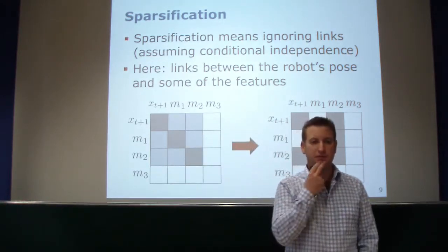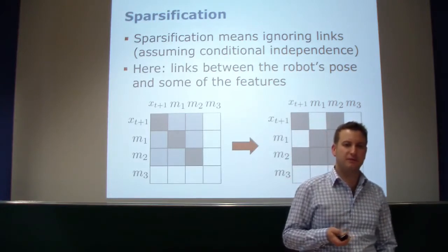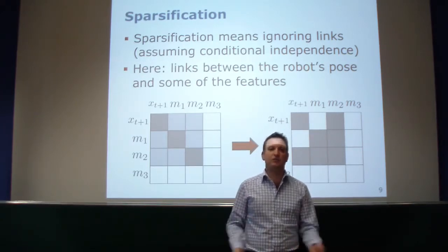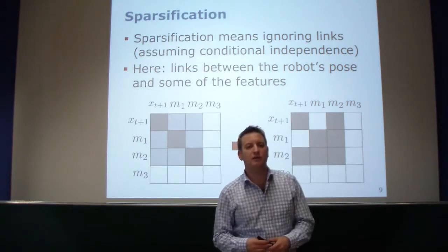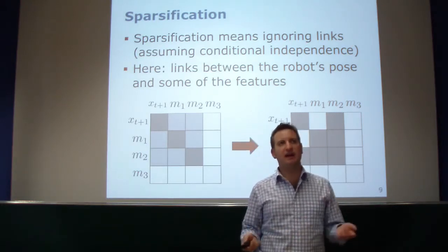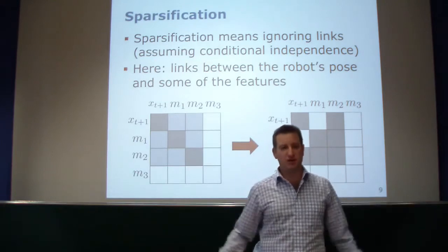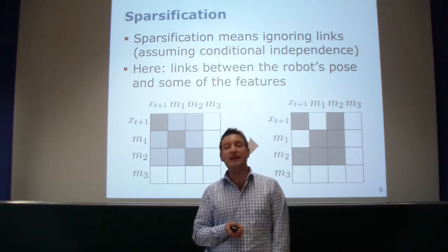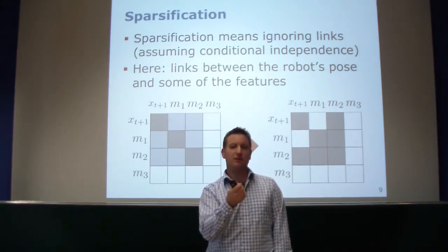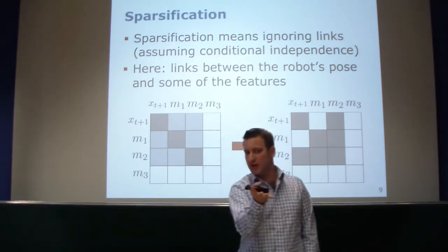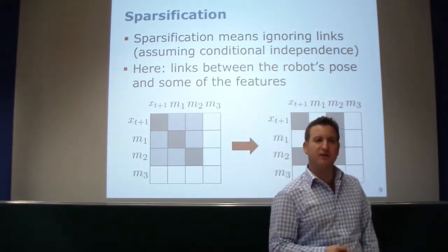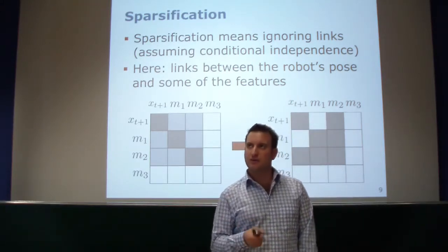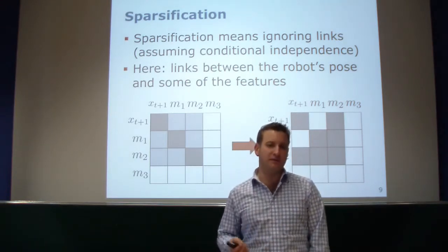Are the active landmarks just the observable landmarks? Not necessarily. Typically you have more in there. Typically you set it to a constant number. Is that a constant number of landmarks? Typically it is constant, but you typically have all the ones you observe in there, plus potentially more. I mean, there's no real need to make it constant. You could also adapt it during operation based on the computation time you have. So that should be possible, yes. The typical implementation uses a constant number, but in theory there's no real reason why you shouldn't be able to adjust this number on the fly.